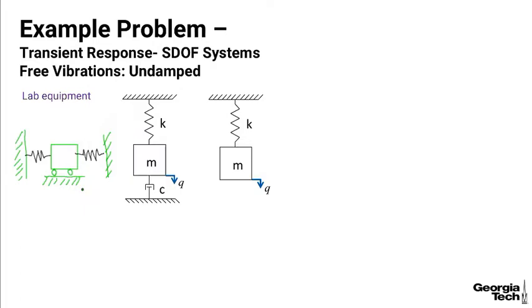Let's say that the spring constant on this spring is K over 2, and on this spring is K over 2. Those springs are in parallel, and so I end up with the same sort of simple oscillator. I have a mass, and I have my support. Now I'm just going to use one support over here. And since the springs are in parallel, this should have been K over 2. Since they're in parallel, now the spring is total K. And so these two systems are completely analogous.